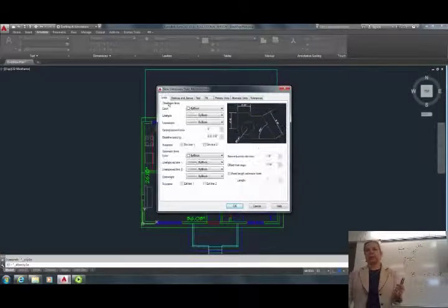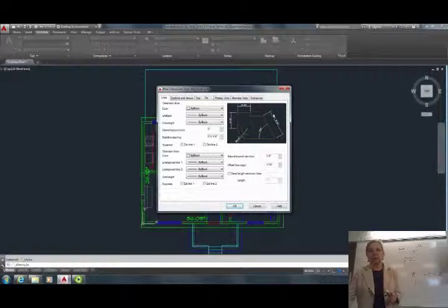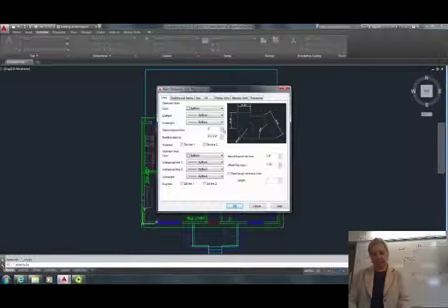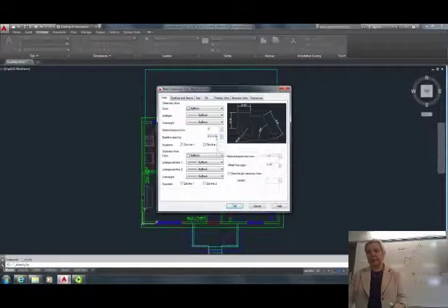Now what's not looking good is I almost don't see my ticks, but my extension beyond tick in both directions also needs to be adjusted. So baseline spacing, you could change it to maybe 1/4 inch if you want to accept AutoCAD throwing in dimensions automatically, but I don't think you're going to have that problem, but let's change it anyway. So 1/4 inch would be the distance between the dimension lines on our small sheets. Again, I'm designing it for my small sheets.